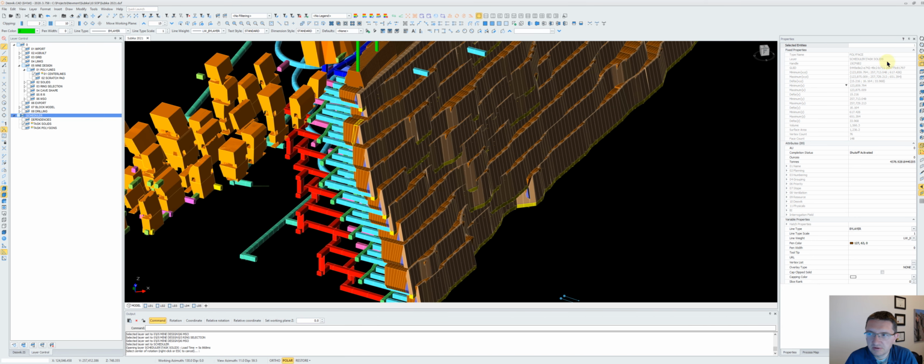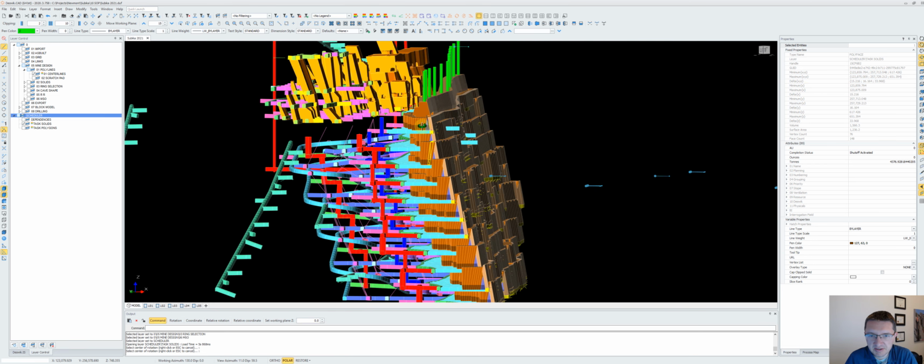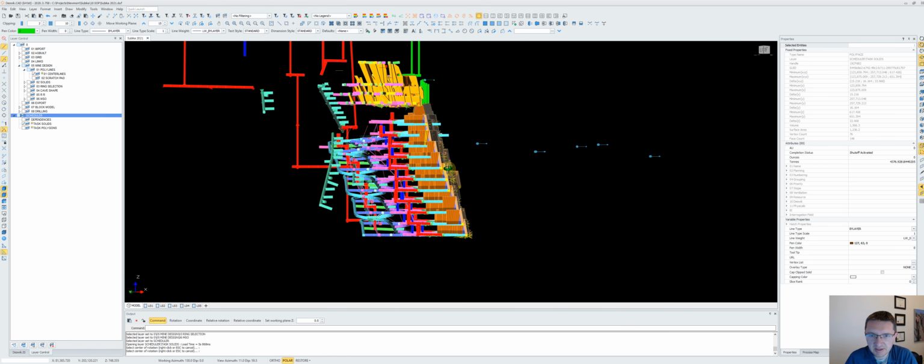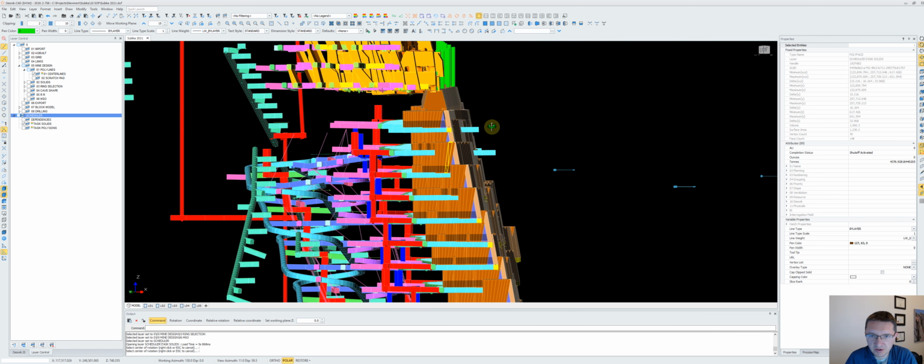We're gonna be deciding where to put all of these rings. The first step, like I said, is to make a master ring set. The master ring set has to extend past what you want, and that way we can turn them on and off, and we can say, okay, these ones out here we're going to turn off, these ones in here we're going to turn on.